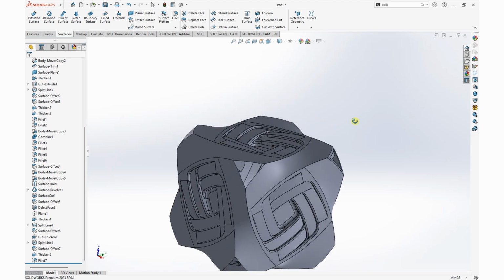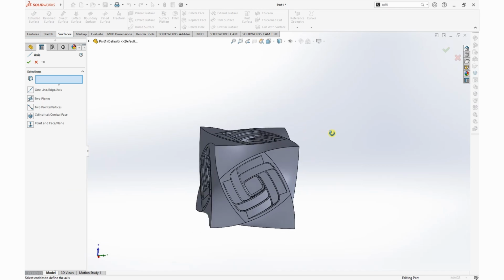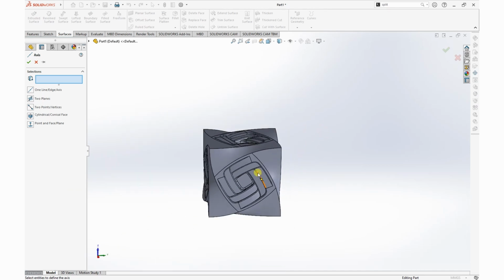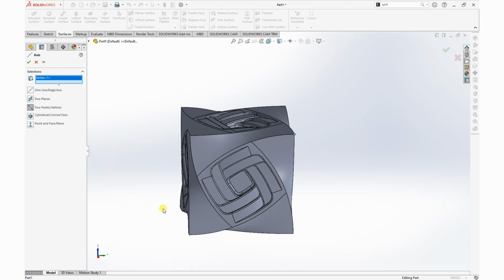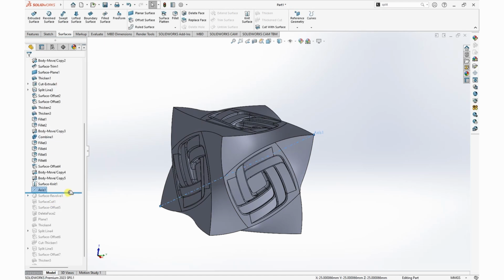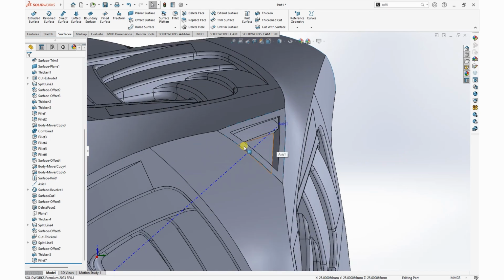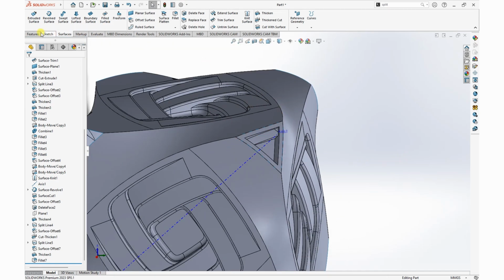So basically, we need to perform what is called a circular pattern, just to ensure those 3 bodies are able to show. So what we'll do is to move the design sheet back to where we added the thickness, or where we stitch everything together, and add one axis running from one corner to the other like that. Then now we can move this design sheet back to the end. You can now see we have this axis. So you want to use this axis to perform circular pattern.